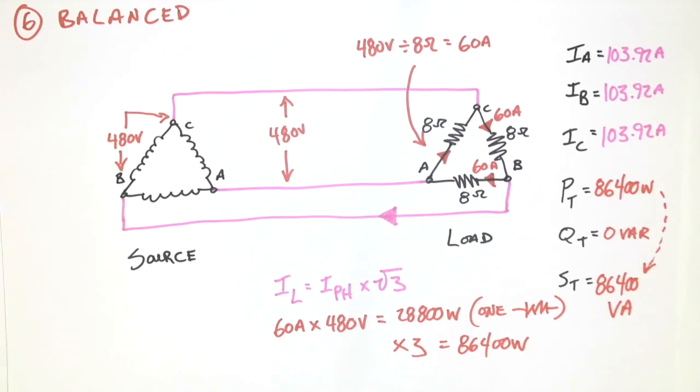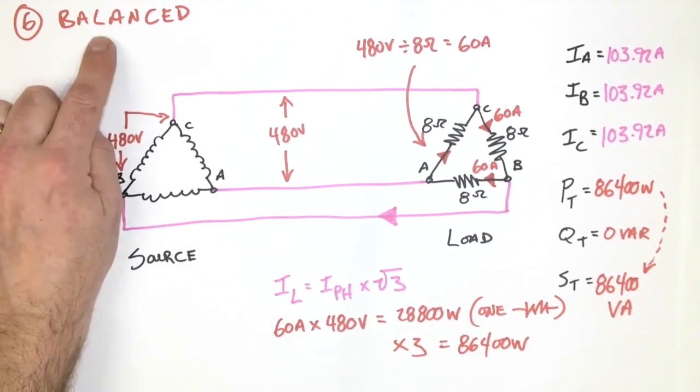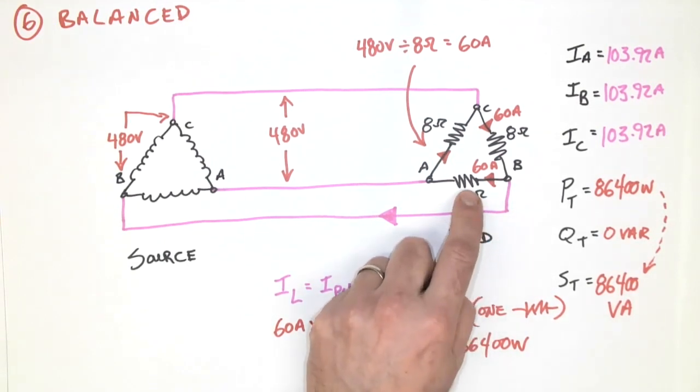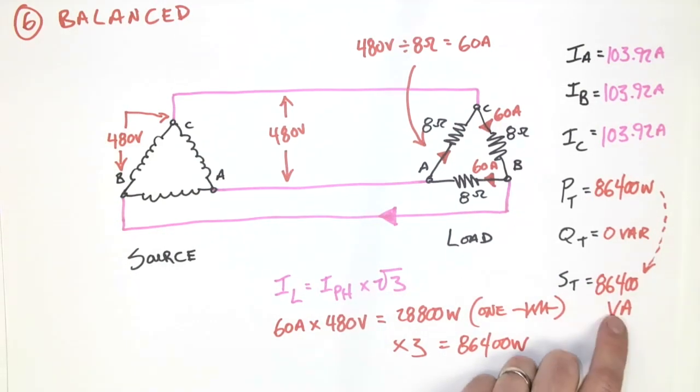Now, three-phase offers some added benefits when calculating with power, especially in a balanced system. So I've shown you one method here that we can use to come out to totals in a three-phase load. We individually calculate the phase values, and after that we add them up, and we may or may not use Pythagoras depending on whether it is a resistive load or something other than that.